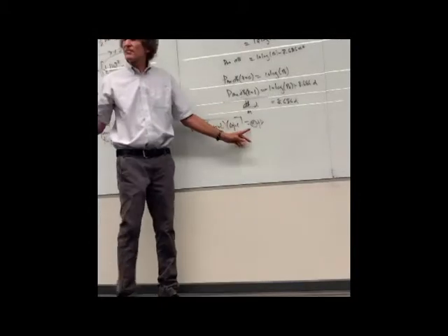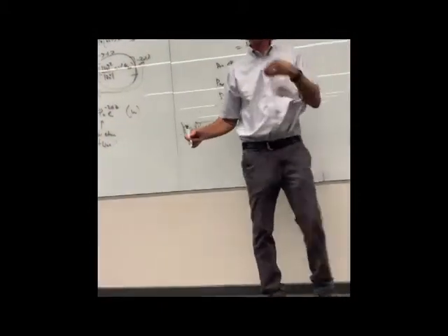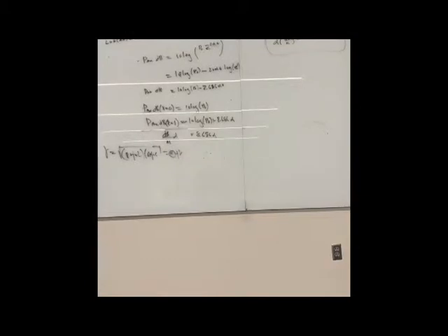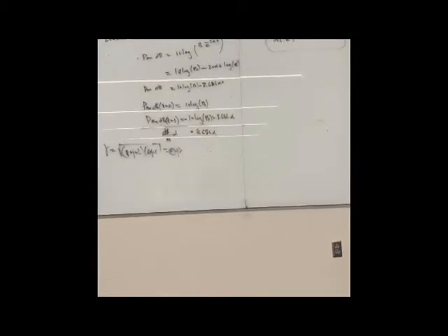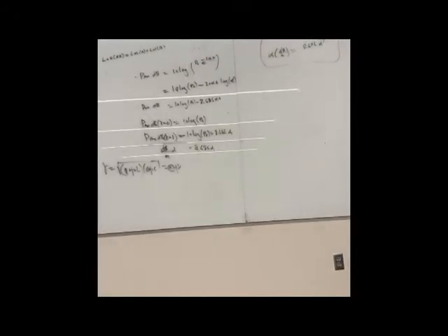So if you wanted to figure out dB per meter, you would take that and multiply by 8.686, and then you would have the loss in dB per meter, and you could easily find the total loss in a 100-meter cable. Just multiply the length by the attenuation in dB per meter. I'm trying to show you things that are useful, in practical senses, for solving problems. All right, next.